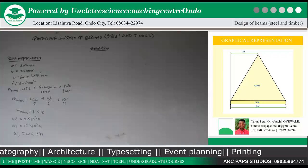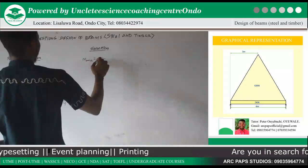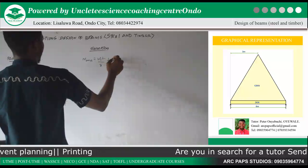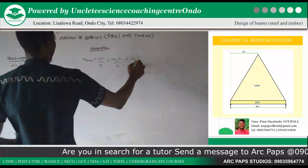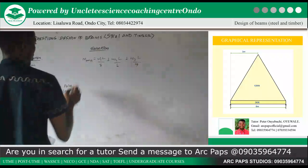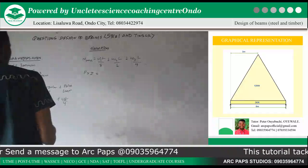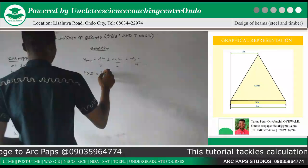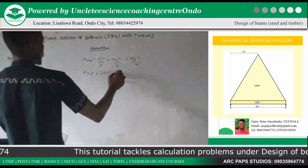Now, in this particular question, we have a triangular load, a UDL, and a point load. So our Mmax will give us W1L over 8 plus W2L over 6 plus W3L over 4. W3L over 4 represents our point load, W2L over 6 represents our triangular load, while the first represents our UDL.